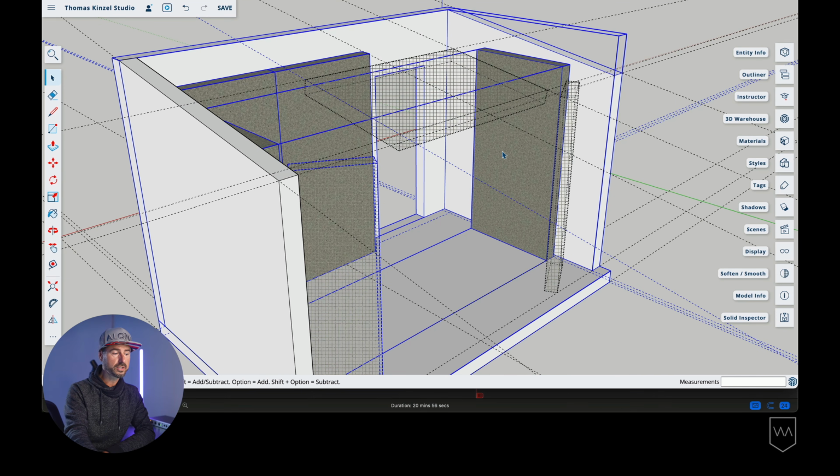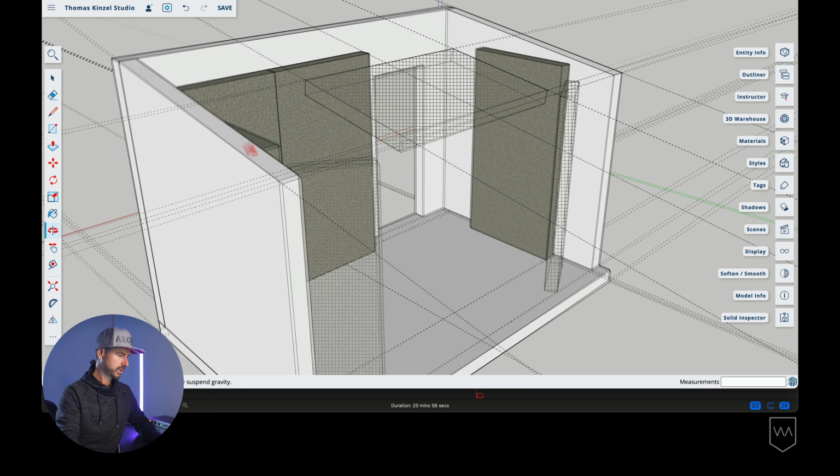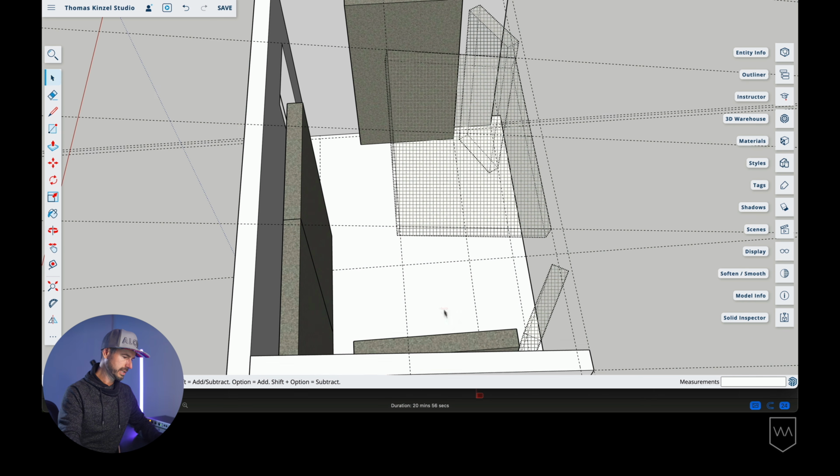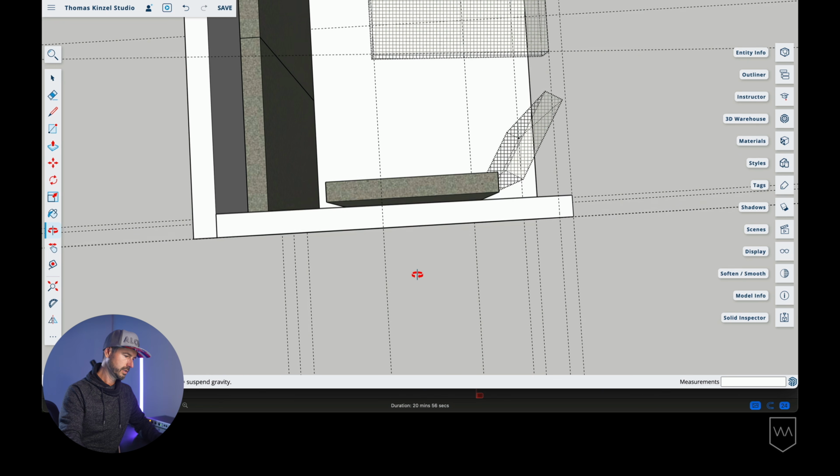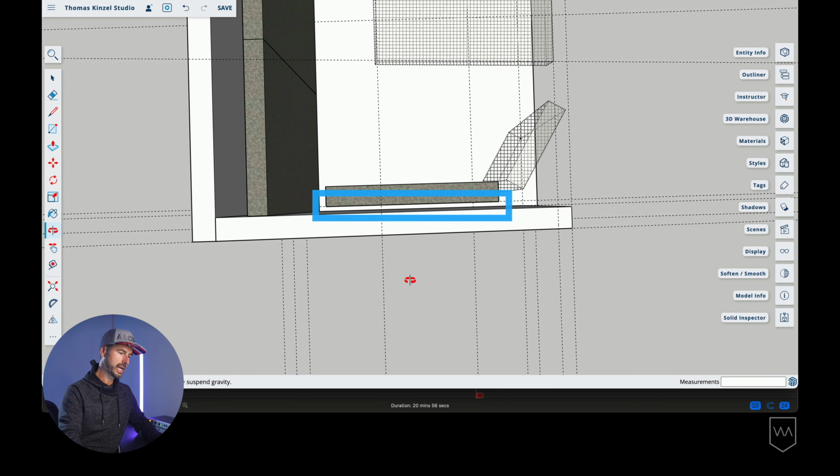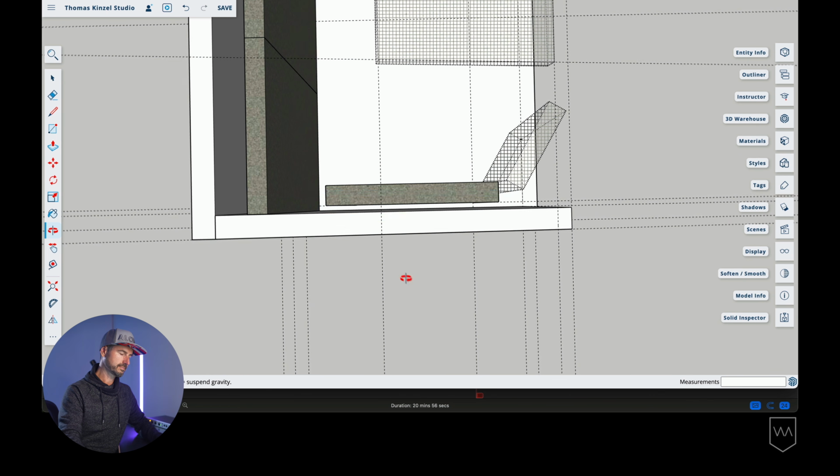The design of these are basically the same as the rear wall absorbers. They are going to be 5.5 inches thick, a 2-inch layer of Rockwool Cavity Rock, followed by 3.5 inches of Rockwool Comfort Bat. They are going to have an air gap, just not as much as the rear wall, because they're not receiving the full frontal impact of the speaker's energy. So if we take a look, top down, you can see there's a little 2-inch air gap with these guys.